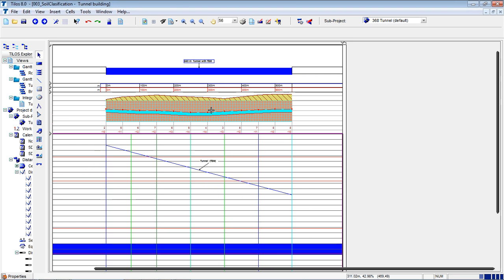This is not a 100% must, but it is important, because when the TBM arrives, I need to at least complete the excavation works to be able to move the TBM from the start location to the end location of the station.